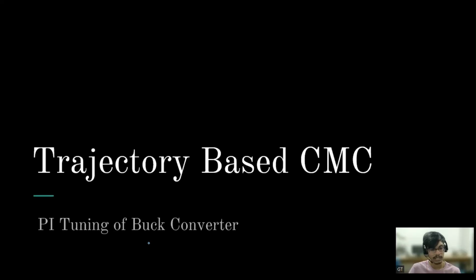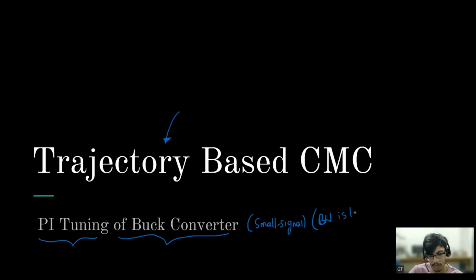So why are we discussing this? Because using this concept, we'll do something called trajectory based current mode control, which is again used as PI tuning of buck converter. Whatever we have learned till now is small signal and it has bandwidth issues. Bandwidth is limited because of the model validity. But if you want to break the limits and achieve higher bandwidth, then you use a large signal based tuning, and it is called trajectory based control.